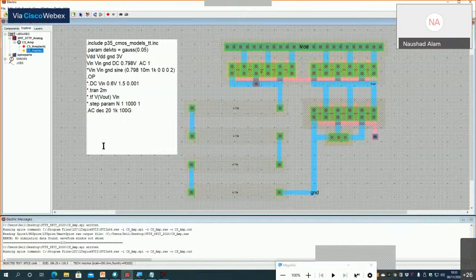So analog design is actually an iterative process. You will never meet the constraints in one pass. For example, I have done only one pass. I did the schematic, I did the layout. So that is one pass. So I am not meeting the specification, and that specification may be from the performance point of view or from the area point of view also.